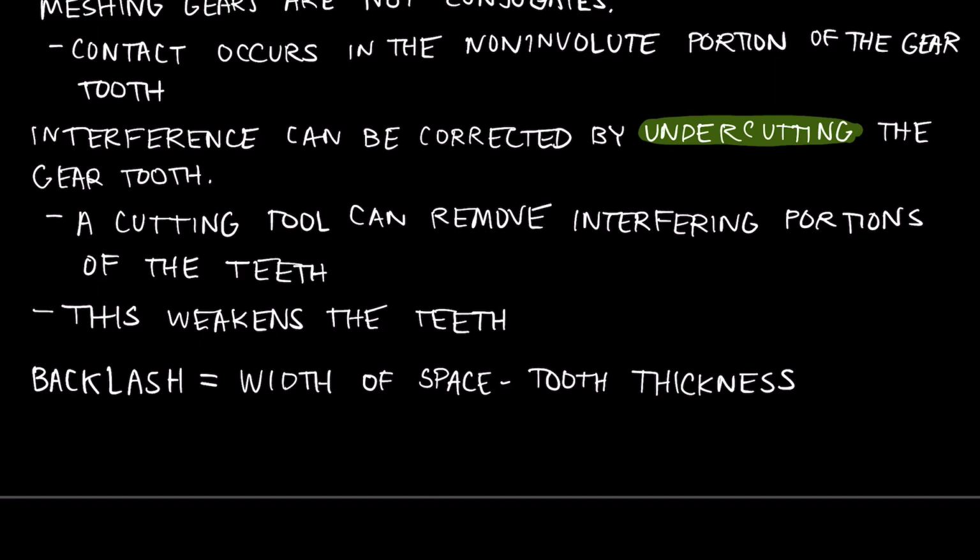But too much backlash can also be problematic, particularly if you are planning on using the pinion both in forward and in reverse. So when we reverse directions of one gear, this backlash, this extra space between the teeth, will get taken up by that backwards motion, and that can cause dynamic forces and impact and all kinds of high loads that could lead to additional damage to the teeth.